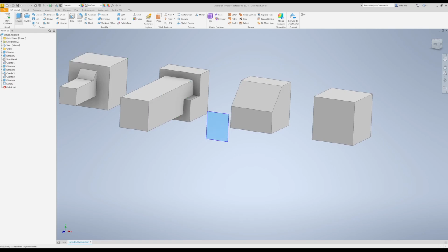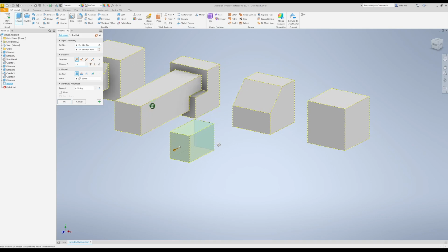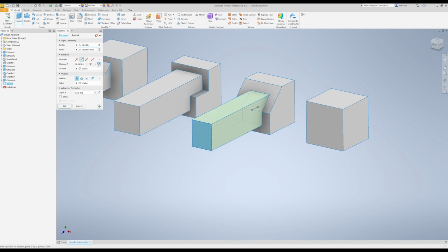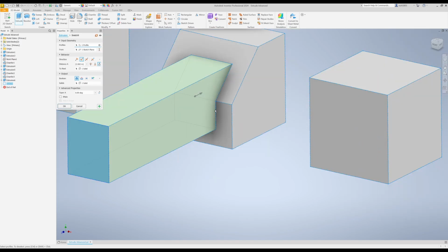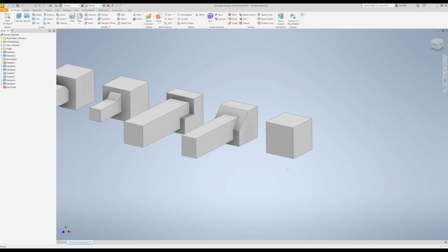Now back to this. Let's go to extrude up here. And since it's the only profile, it's auto-selecting. I can go to, well, let's face it this direction. And to next. As you can see, it will only go up to this surface. Very helpful. If I go through all, it'll cut all the way through. Same as before.